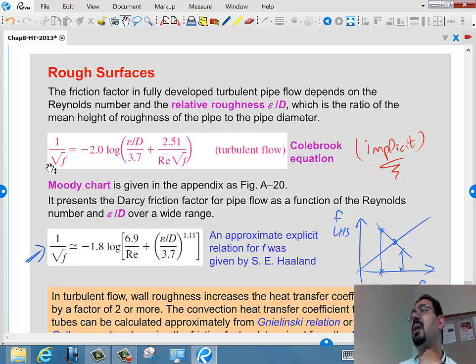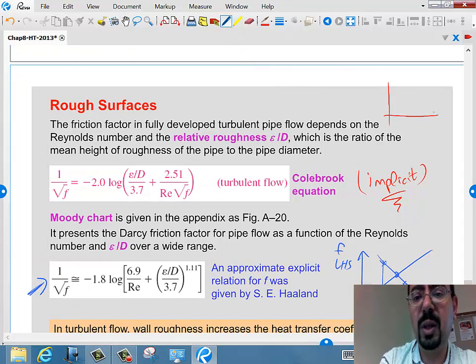So anyway, here he calculates the friction factor. I'm not going to ask you to calculate the shear stress for me, right? But know that there is a correlation to calculate the shear stress, or the pressure drop. They are two faces of the same coin. And the way to calculate this is basically f, the friction factor. Remember from the Moody chart? For laminar pipe, how much was it? As a function of Reynolds, it was 64 over the Reynolds.